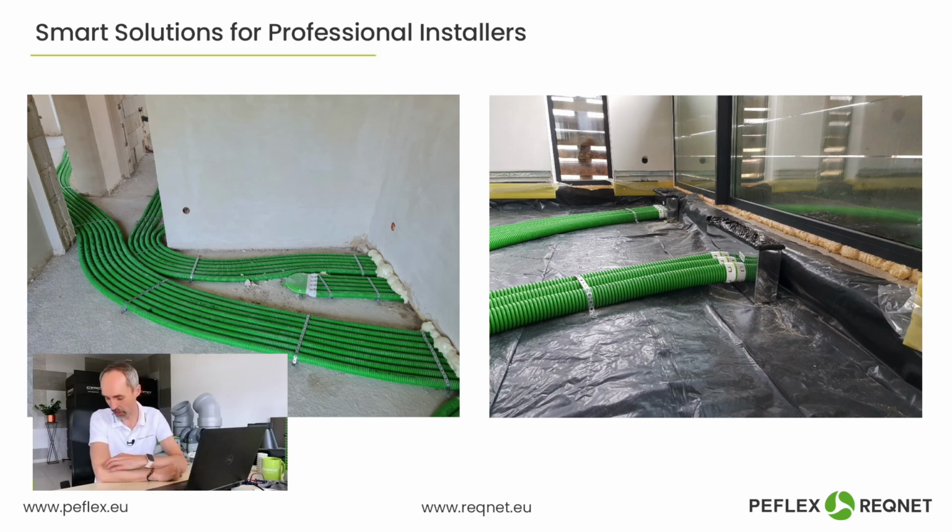This is, among other things, what it can look like when using 50mm pipes, where, in order to achieve the right efficiency and the right amount of airflow, we have to use a lot of these pipes, and sometimes there just isn't enough space in the area we want to use for air distribution. And as I mentioned, we can also supply air from the floor by using, among other things, slot diffusers mounted in angled boxes for slot diffusers, located, for example, under glazed areas like balcony doors or any other glazing. Right?